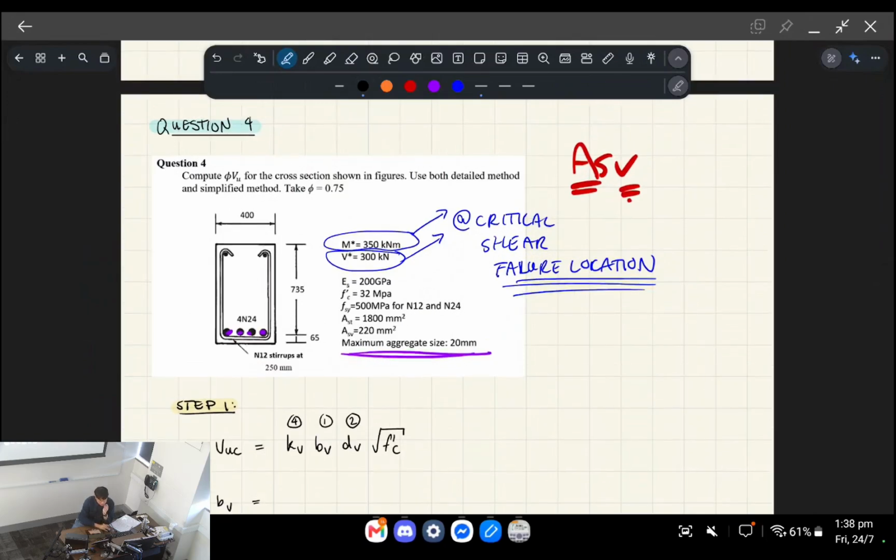Okay, so looking on the left screen, one thing which I forgot to point out before: to find the total shear capacity of a reinforced concrete beam, it's in two parts, right? The first part is the contribution due to the concrete without any steel, and then the other part is what the steel contributes to the strength as well. Okay, so the notation is VUC added to VUS.